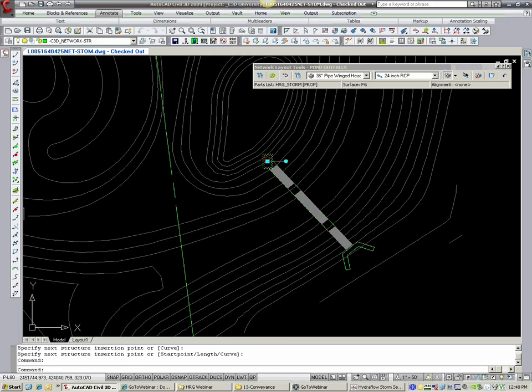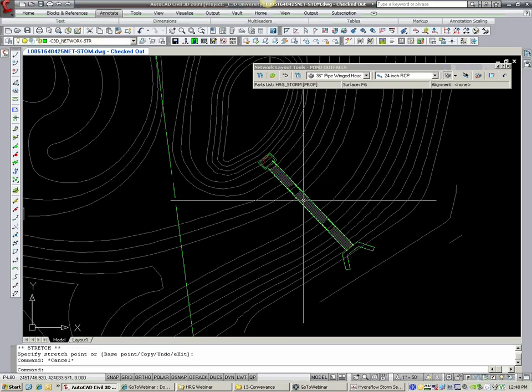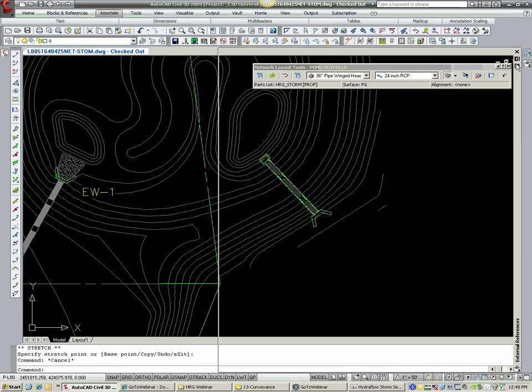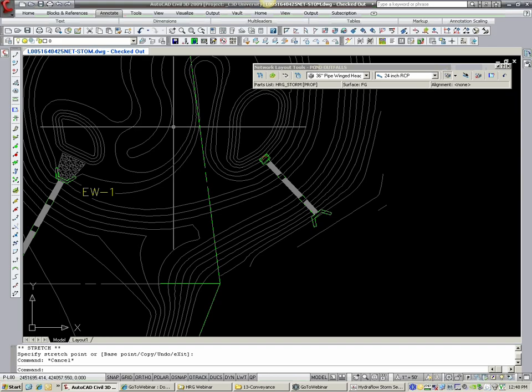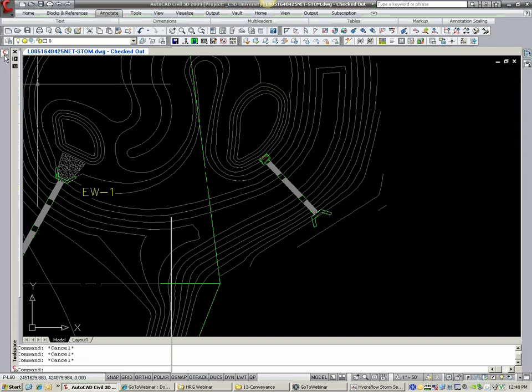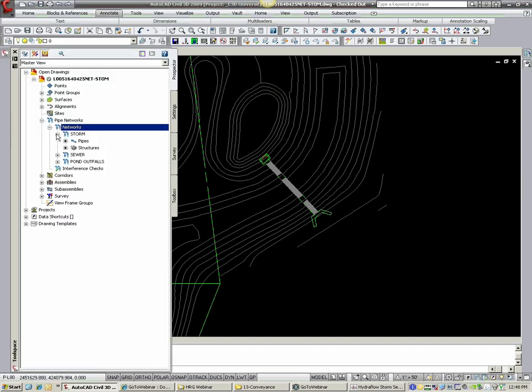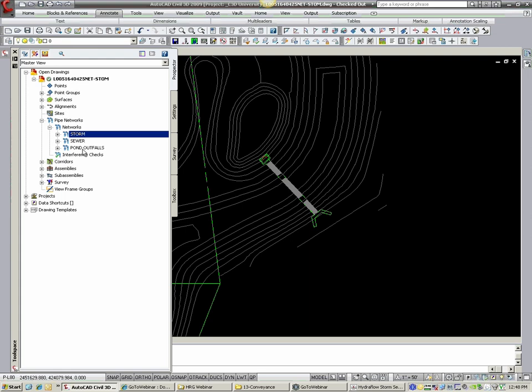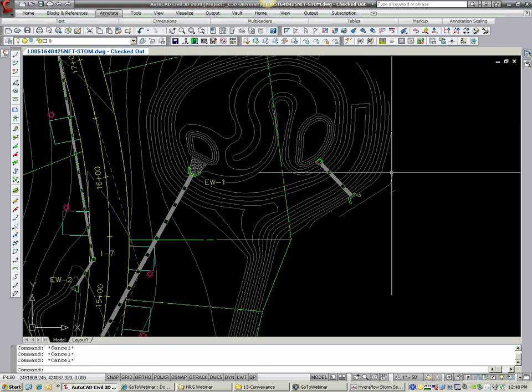Outfall is now drawn in for Civil 3D purposes. You can make a profile of that, do whatever you want, but technically that outfall, you go back into Prospector now, is in a totally different network. So when you make the XML, you don't get those outfalls. That's what I recommend to do there, definitely. Okay.